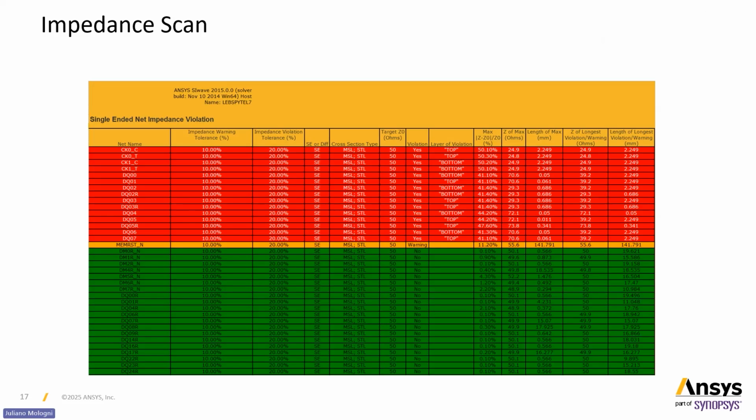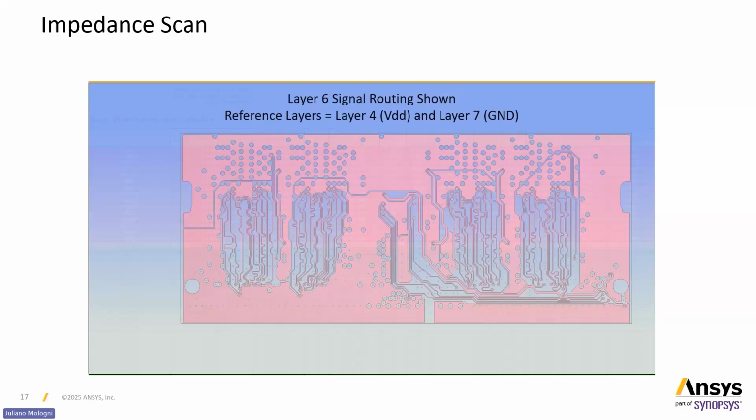We can also look at the impedance and crosstalk. When you're designing your PCB for high-speed serial channels, you design for a specific impedance, let's say 50 ohms for single-ended nets or 100 ohms for differential nets. And you have equations that you can use based on the thickness of your dielectric, the Dk, and also the width and the thickness of the traces. But is that easy to do on an entire board? Sometimes you might just use the same width from a microstrip to a stripline, from the top layer to an inner layer. And they have to be different widths if you're using the same dielectric.